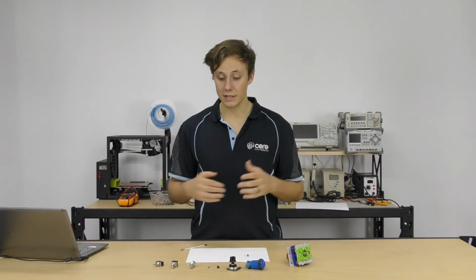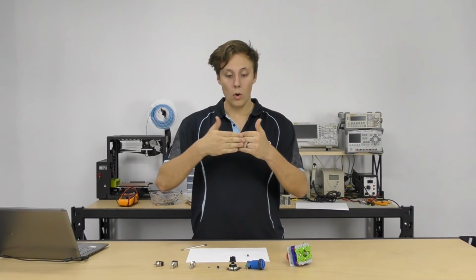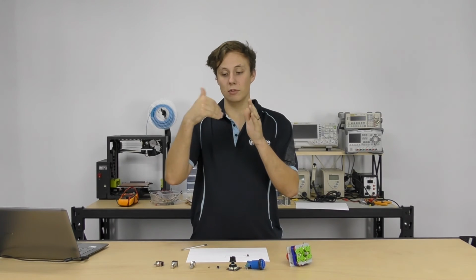But because they are big and weighty, they have more momentum. As we said, momentum is a function of velocity and mass, and the greater the mass, the greater the momentum. The greater the momentum, the more inertia they are going to introduce into the system, which causes bouncing. So a really small switch might only bounce a tiny bit. A really big switch might bounce quite a lot, which gives you a longer time period. So what you have to do is use debouncing.